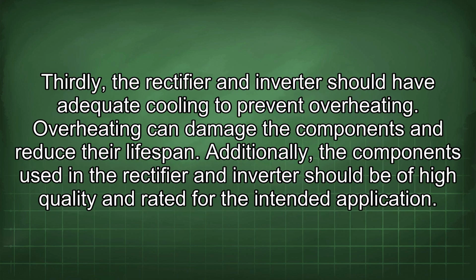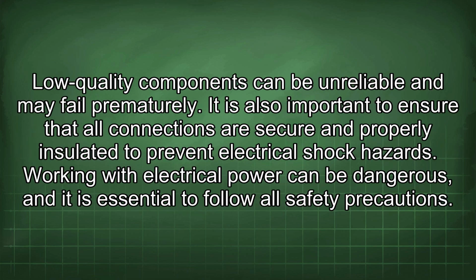Thirdly, the rectifier and inverter should have adequate cooling to prevent overheating. Overheating can damage the components and reduce their lifespan. Additionally, the components used in the rectifier and inverter should be of high quality and rated for the intended application. Low-quality components can be unreliable and may fail prematurely.